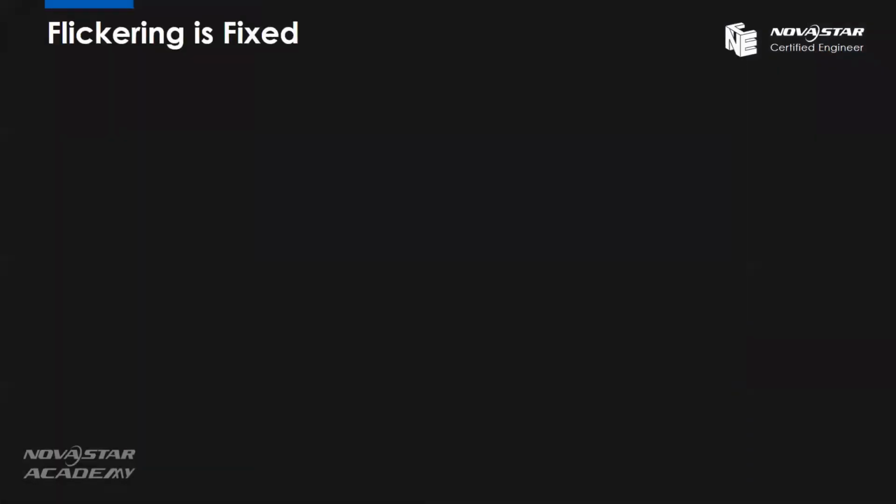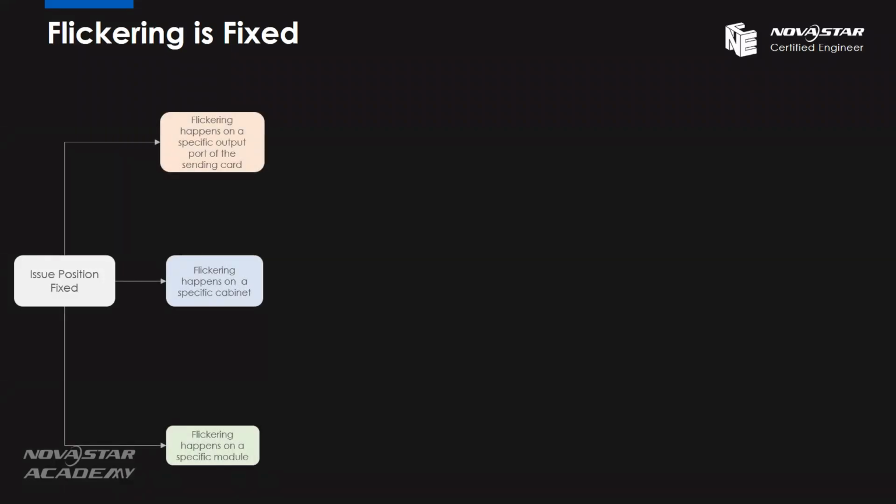First, if the flickering position is fixed, which means the flickering is not random and only happens on a specific area of the screen, it could be these 3 situations. The first one, the flickering happens on specific output ports of the sending card. The second one, the flickering happens on a specific cabinet, or you can consider it the receiving card. And the third one, the flickering happens on a specific module. Let's see them one by one.